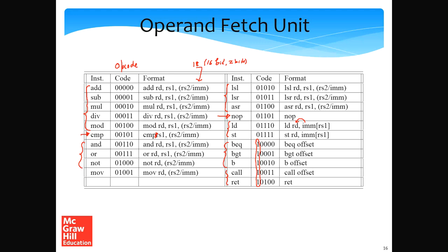To find out if an instruction is a load or a store, you will see that they have been given consecutive opcodes. So we actually need to look at the first 4 bits. If the first 4 bits are 0, 1, 1, 1, then we will know it's a load or a store. That will also tell us that we need to access the memory access stage. And similarly, we have a quick way of finding if an instruction is a shift or something. Essentially, in opcode design, we have to look at how easy it is to understand and how quickly we can decode an instruction.